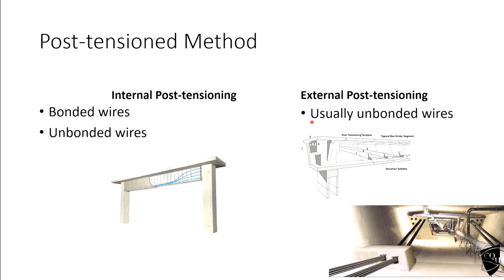So I need to find out the main objective. There are some other things, but the main thing is to find out the suitable section, the pre-stress force, and the location where we have to apply it. So these are the three main important parameters I need to find out.